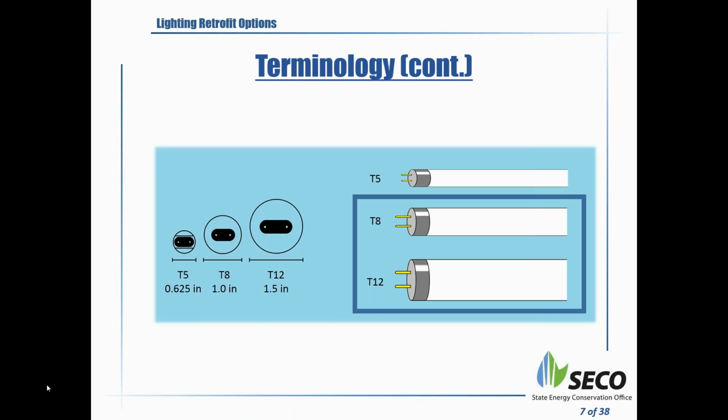You see them in a box because if you all remember, around 15-20 years ago, you used to have 40 watt T12s with magnetic ballast, and then there was a movement to lower wattage, which was called the 34 watt and the 32 watt T12 lamps, and these are pretty much out of the market now. T8s were the thing to do at that point in time, and there is a substantial amount of T8s. Almost everywhere you're going to run into T8s nowadays. So the T8s were the retrofits for the T12, basically.